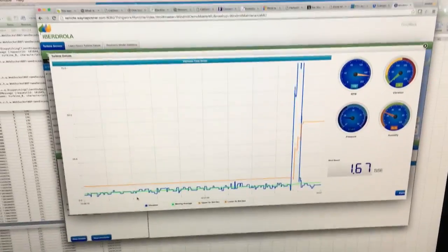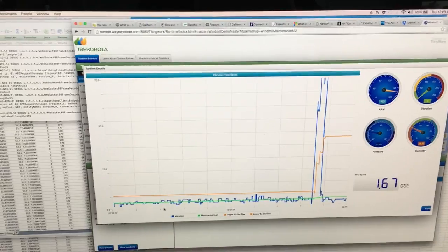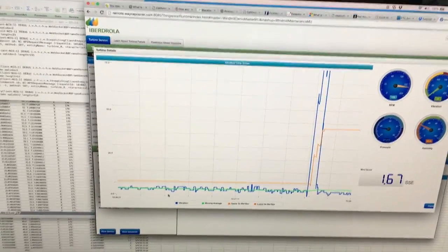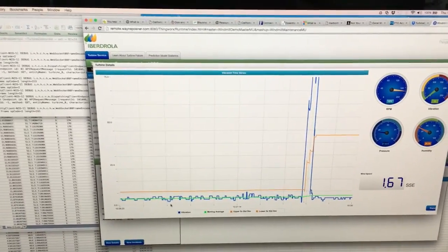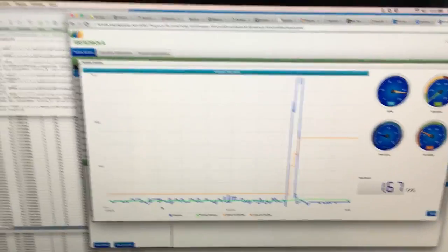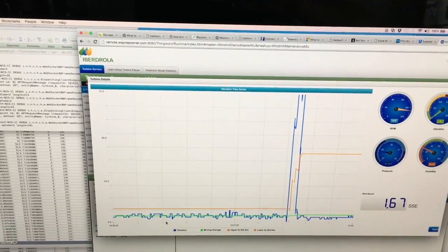But I mean, if that actually happened, let's see what this would show up on the graph. Okay, so there's a major spike, I mean, beyond anything that we would ever expect in this vibration time series. You can see that spike's represented by the blue lines. The standard deviation just went up significantly because it completely threw off the variance average.